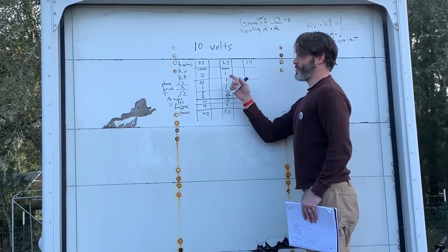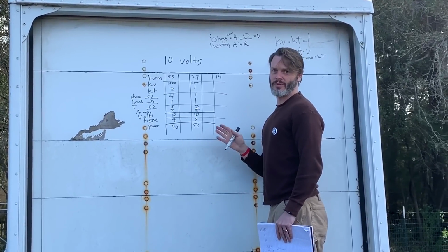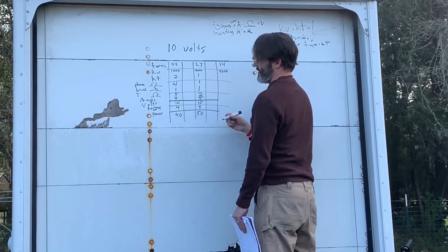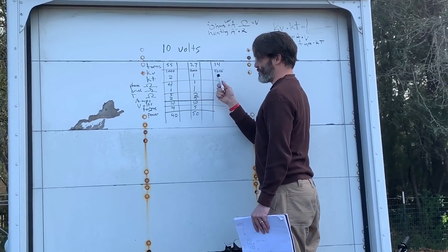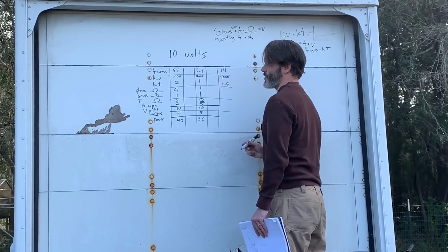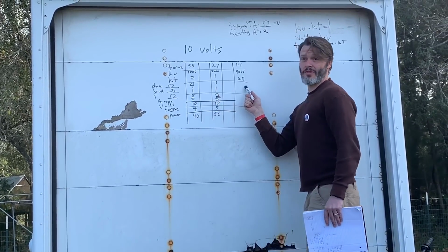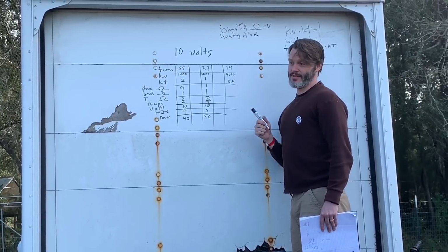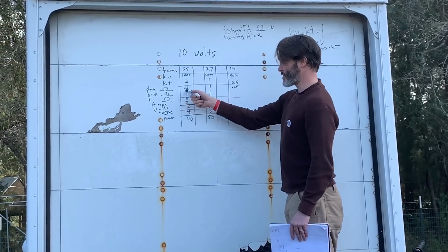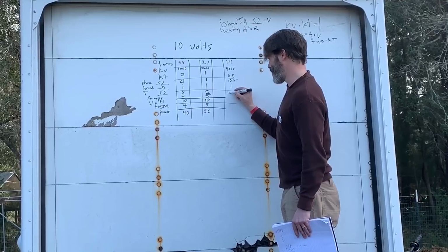We're gonna double our motor speeds. We're gonna go from 2,000 kV to 4,000 kV, about a 14 turn or 15 turn motor is the right speed. So we're gonna start here, 4,000 kV. KT, we doubled our motor speed, so our KT gets cut in half. This is going to be 1/2 unit. Our phase ohms here, we started at 1, now we're going in the other direction. What do y'all think is gonna happen? Yeah, it's gonna be a quarter. Exactly, so 0.25. Our brush resistance did not change. Our total ohms on this motor is now 1.25 ohms.